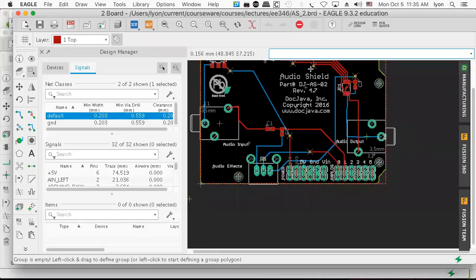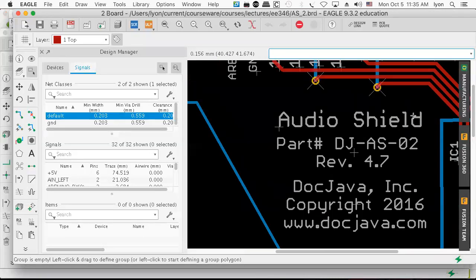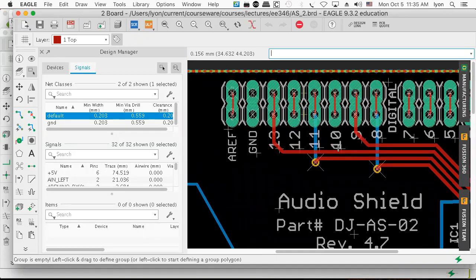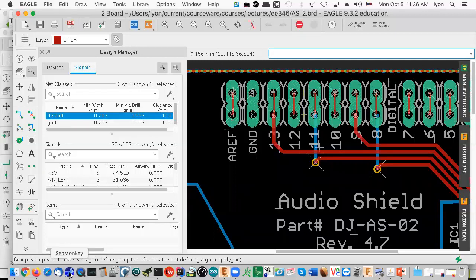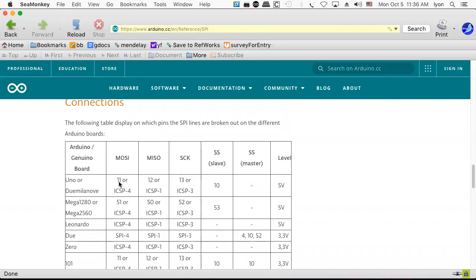Over here, you can see where the pins are actually wired, and how the different pin numbers have been dedicated to different SPI functions. What's going on with pins 9, 8, and 11 is something you could see with relative ease over in here, where he's saying for Uno, MOSI is 11, MISO is 12, so we skip it. You can see how these things map.